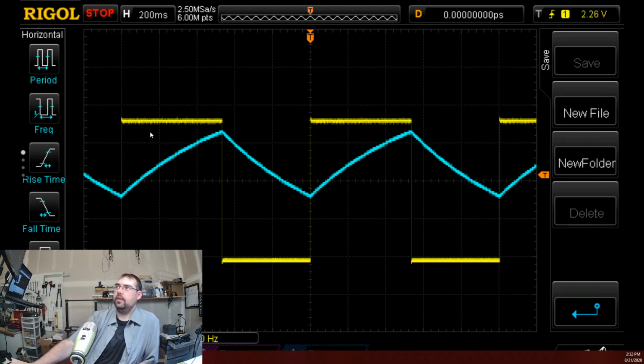So for our period, let's think of a circle. Let's say you're going to run or walk around a circular track. You're starting at the top, and you run around it, and you get back to where you first started. That would be considered 1 period. 1 cycle has been completed, and you can visualize this here. Let's look at the starting point here. This is where it went high, and this is 5 volts high, and this is 0 volts low. So it goes 5 volts, turns on, then turns off, and stays off for half a second, and then turns back on.